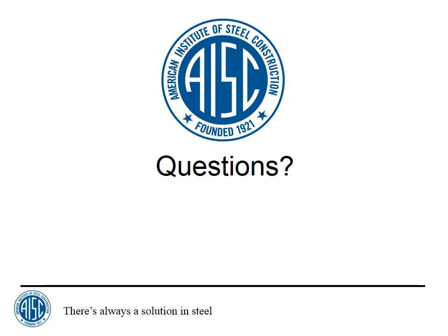If there are column stiffeners, you could probably eliminate prying action, but in order to do that, you would have to have a stiffener, I think, between every pair of bolts. Maybe between every other pair. I've not really looked into that, but you can't just have a stiffener, let's say, at the top of the connection and at the bottom of the connection, because you got all those bolts in the middle. So this might happen, for example, where you've got a moment connection that frames to the column web that's exactly opposite the beam to column connection that frames to the flange.